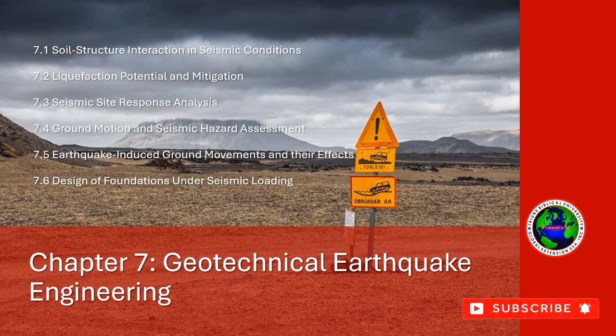Liquefaction occurs when saturated, loose sandy soils lose their strength and behave like a fluid due to strong seismic shaking. This phenomenon can result in significant ground displacement, where structures may tilt, sink, or float, and can lead to the formation of sand boils or fissures.